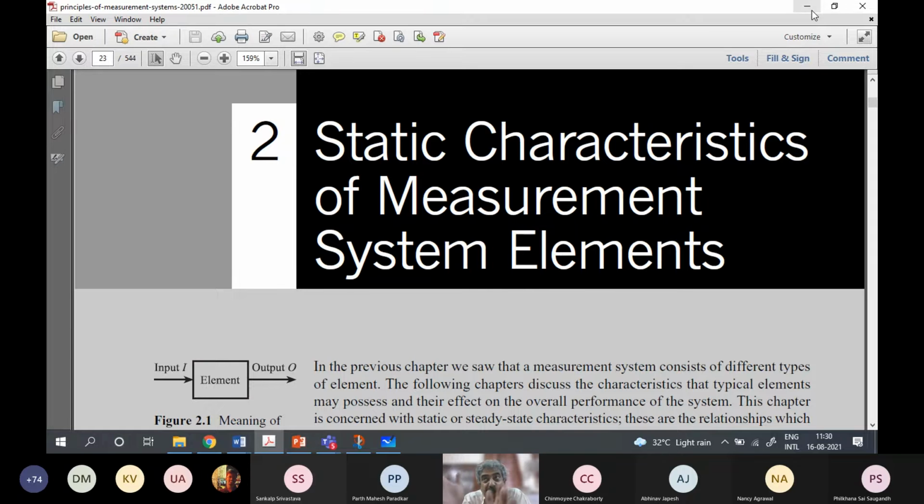So, this is an interesting point. If you think of the instrument as a system, then when you read its data sheet, you will always see that if it is given a temperature of 200 degree centigrade, its output is going to be between 199 and 201 degree centigrade. That is what will be stated in the data sheet. But you have to use that to understand that if you get a reading of 200.2, then what is the range in which the true temperature exists? So you have to invert this map. This is very important to understand.